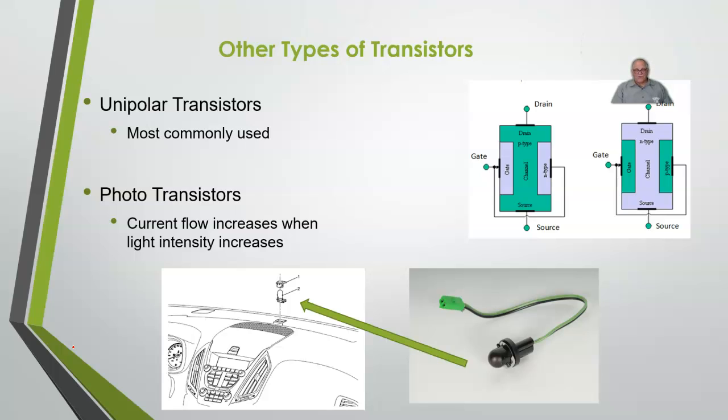They're actually a unipolar transistor, which I chose this particular drawing because on this one, our voltage is going to flow right down here through the center from the drain to the source. The drain was our now emitter, source is the collector, the gate is the base. They changed the names on you. But the current that's going to flow through there flows through either a P-type material or through an N-type material, not both. Hence the name of unipolar instead of bipolar.